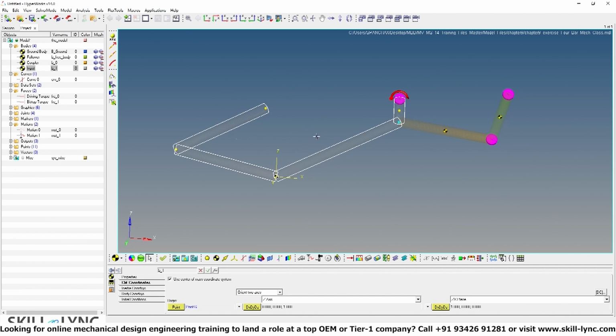Now, once you've created all this, it's time for you to create outputs. You can create outputs on bodies, points, joints, and markers. Okay, you can also directly request the force, bushing, and spring damper entity outputs. Another way to create the outputs is using mathematical equations. So in this step, you'll be adding a displacement output between the two bodies using the default entities.